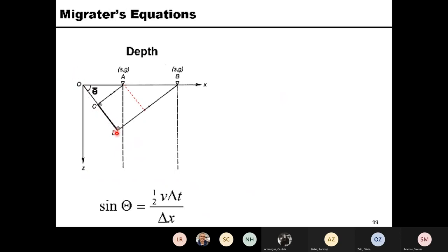In the model space, if we have a reflector, which is length from C to D, the CMP point, S and G, S means source, G is geophone, they are at the same position, so CMP A. The A point has a ray path perpendicular to the reflector at point C. That's 90 degrees, yeah?